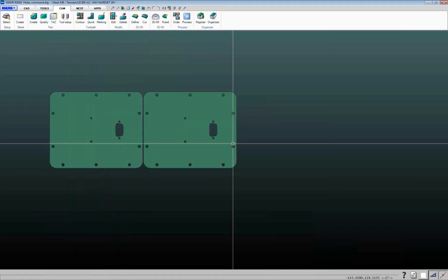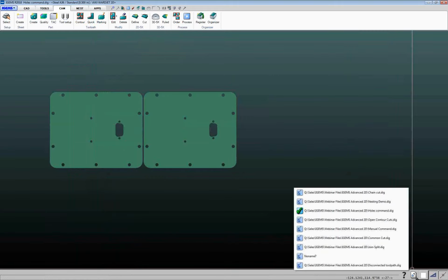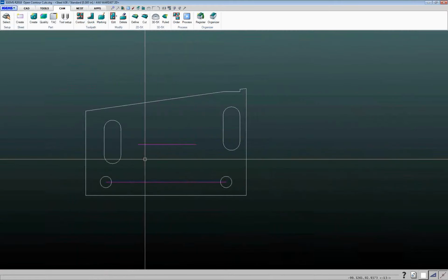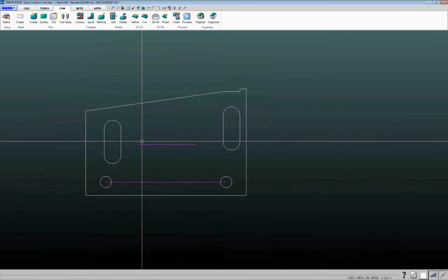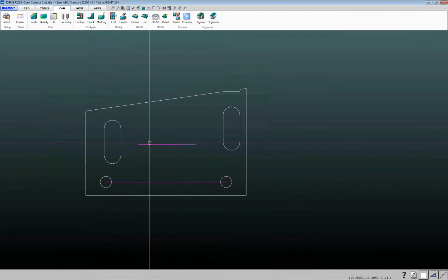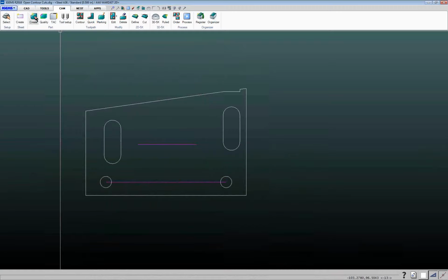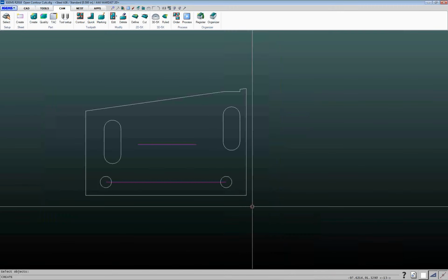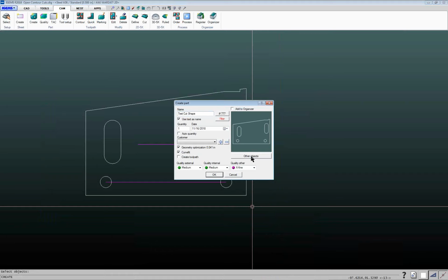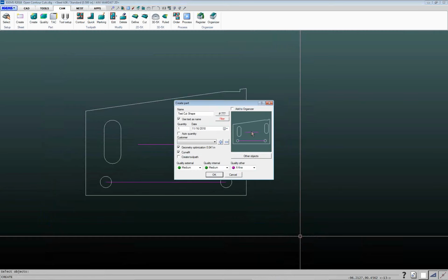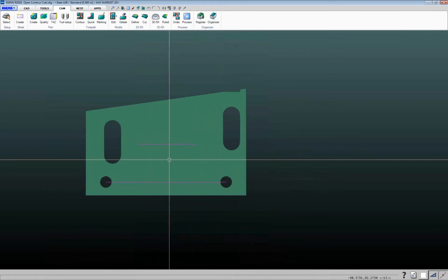All right, then next review the open contour cuts command. So oftentimes we'll get one where people want to either cut or mark open contours on a part. So these lines here, what we consider open contours because the endpoints don't match up. So if you want to cut or mark things like that, when you create your part, click on this Other Objects button, and then select those entities. They'll show up here in the preview with the magenta lines, and then you can add toolpaths to those things.